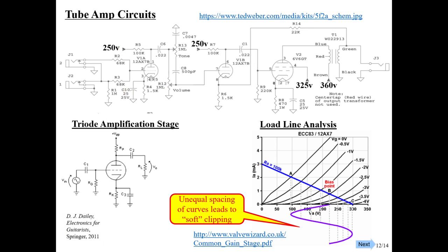It's all driven by the voltage here relative to the cathode. And so as that changes, we're operating on different curves. So the VA is the voltage at the anode to the cathode. So if we were to fix that, say, at 100 and put VG at 0, we'd be operating at that point. Here's a decent bias point.